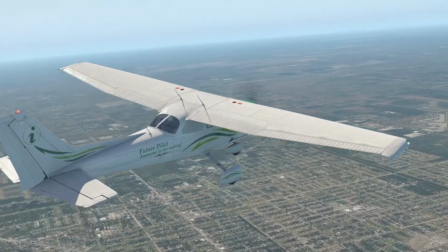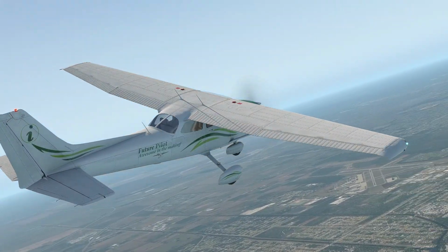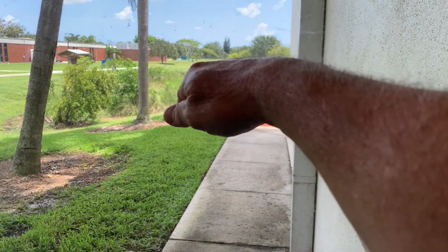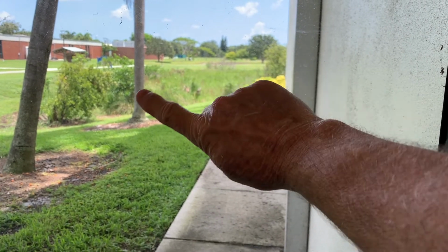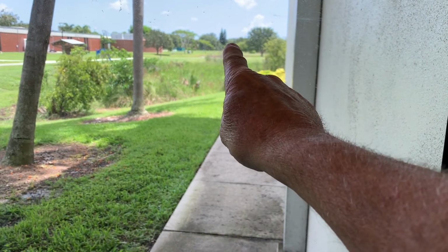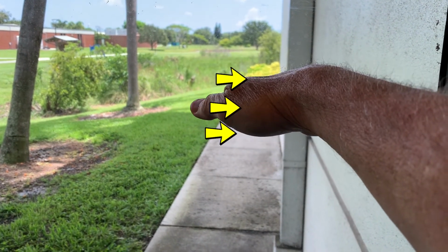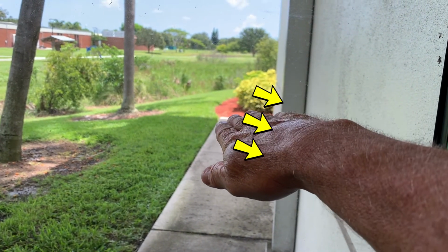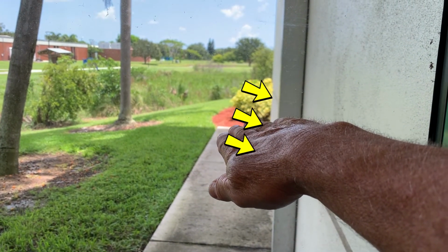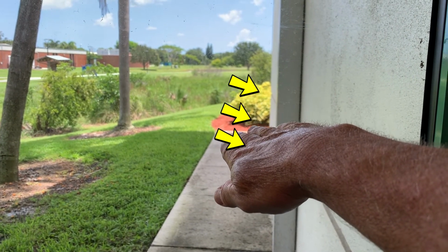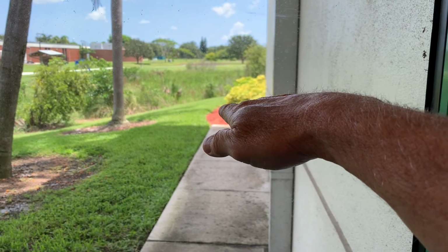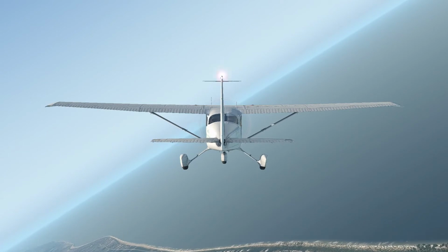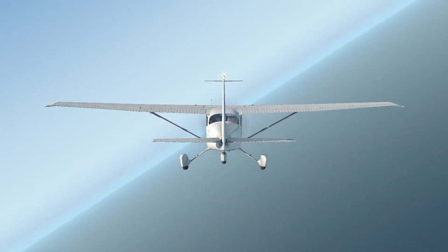Control surfaces are parts of the outside of the aircraft that will alter the aircraft's relationship with the air around it. An example I can use is if you have ever stuck your hand out a moving car window, which I highly discourage because doing it is dangerous. But if you have and your palm was flat, it would simply glide along the air. But if you tilted your hand down, the air pressure now on top of your hand would force your hand down. You have just altered the condition that your hand and the moving air shared. These conditions between the aircraft and the air are controlled through control surfaces. Let's look at what they are on the airplane.